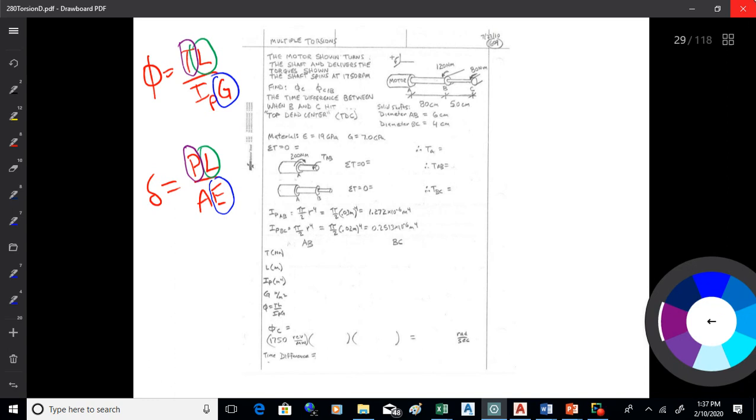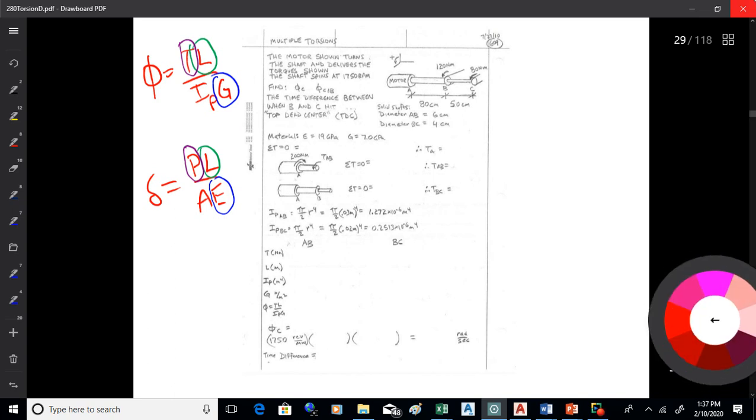And then also we have the primary shape property that resists the load. What resists the load when you pull on it? How big it is, the area, right? But what resists the load when you start twisting it? The moment of inertia. See, those are analogous formulas. They're just for different situations. The one on the bottom is for stretching something out. The one on the top is for twisting something. But they have the same sort of things you put in, just slightly different versions because they deal with different situations, okay?